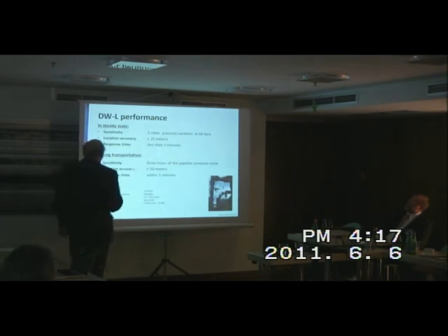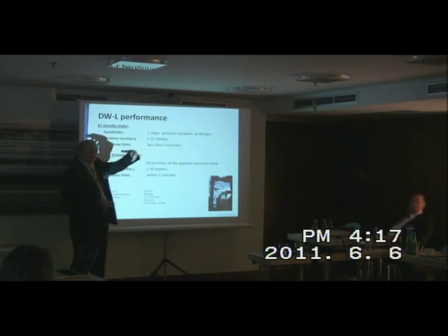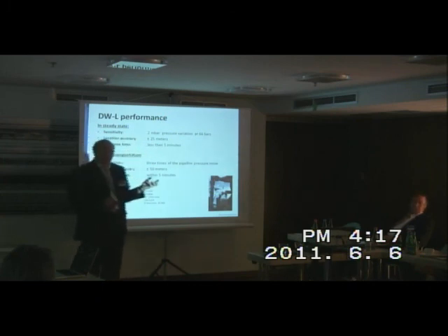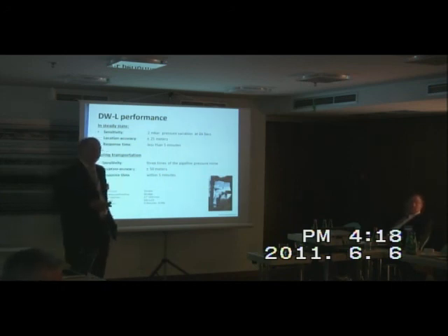If we compare, our sensitivity of 2 millibars cannot be measured with a normal pressure transmitter. Only 20 or 30 or 40 millibars is measurable, to make a difference between two. The competition can measure from 30 millibars, yes.